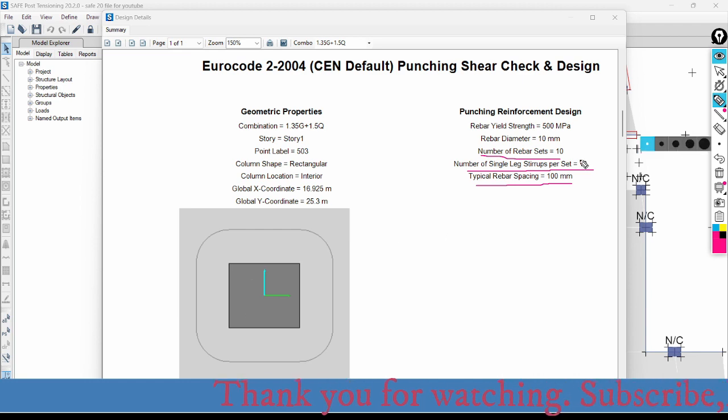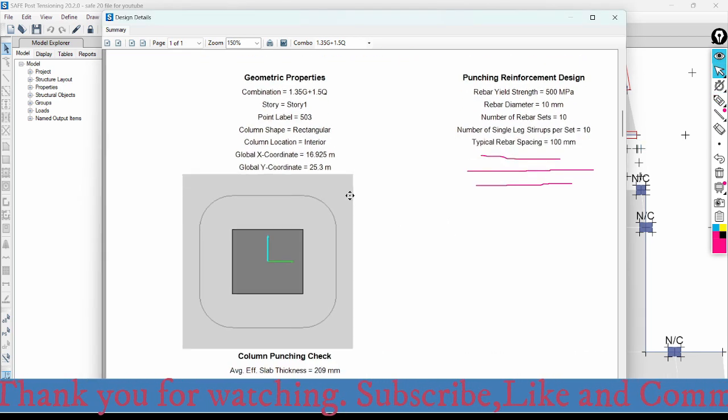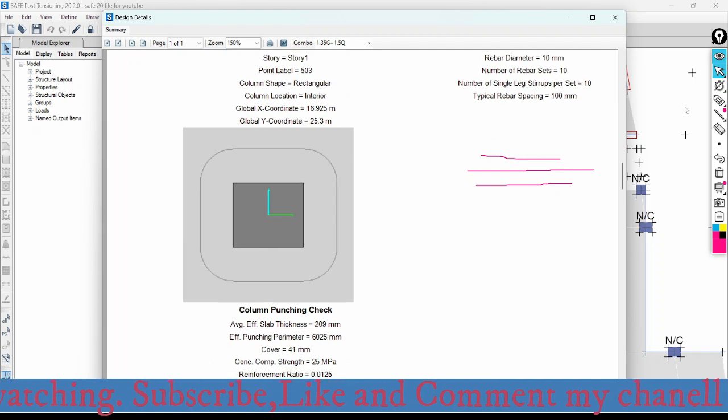Here, sorry. So first I need to put the number of rebar sets here, 10. So above the neutral axis here, we have 5, and below we'll have 5. Totally, how many rebar sets are required? It is 10. Because this column is an interior column.